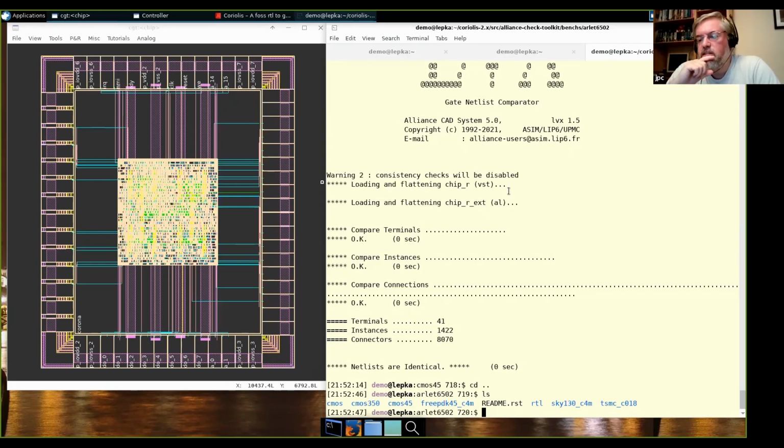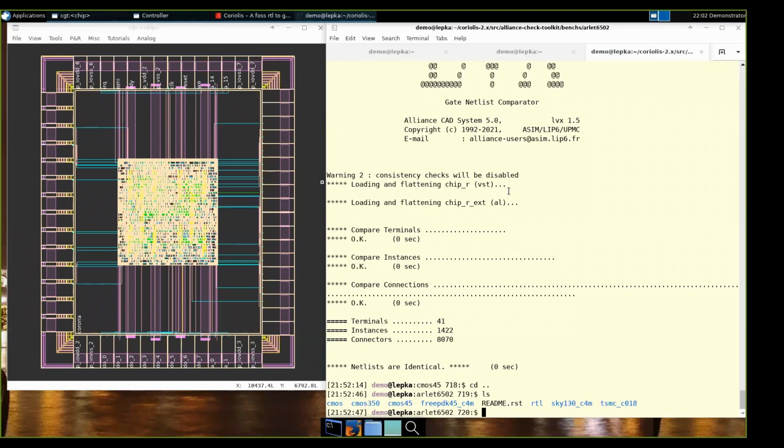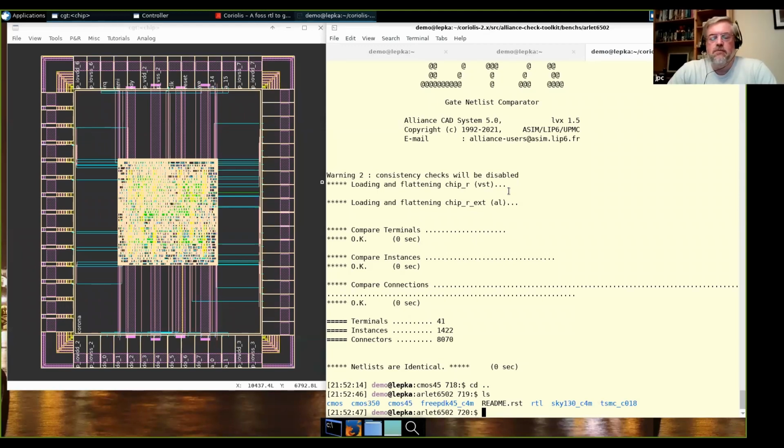I think we will explore it again in some way. What you are defining is some kind of progressive refinement. That is, you don't place, then global route, then detailed route, but you make a rough placement, make an estimation of the global routing, and then go on. Do I make myself clear or not? Yeah, it's fantastic. It's clear in my mind. So it's a very important feature.